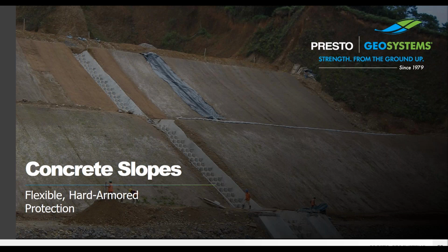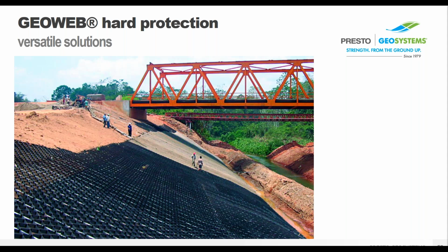And then the last infill type is concrete. So concrete, again, it's not going to be permeable like stone, but it's still considered a hard armor solution. But there's still going to be no maintenance requirements with concrete, and the embankments are going to be able to handle really significant amounts of water runoff. And that's kind of going to be the big focus of why you may choose concrete over stone or soil, is if you know you're going to have a lot of water movement.